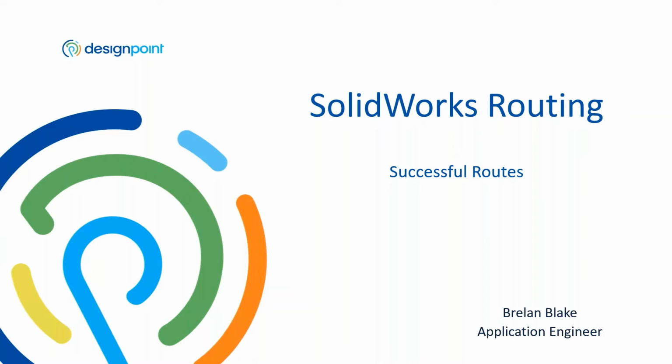So you would need to turn on your routing add-on in your add-on options to activate your route menu. And then you're going to have different disciplines at the top of your menu, and then you can drag and drop and begin your routes. Okay, so if you hear me go on to say about the routing library manager, any routing component that has already been processed through has a C point established, which you see at the front of your screen, right in the center of those points. They're standing in as a routing C point. And your routing C point is going to be ultimately your starting point, and then you can process all the rest of those through, and then your route will actually begin.